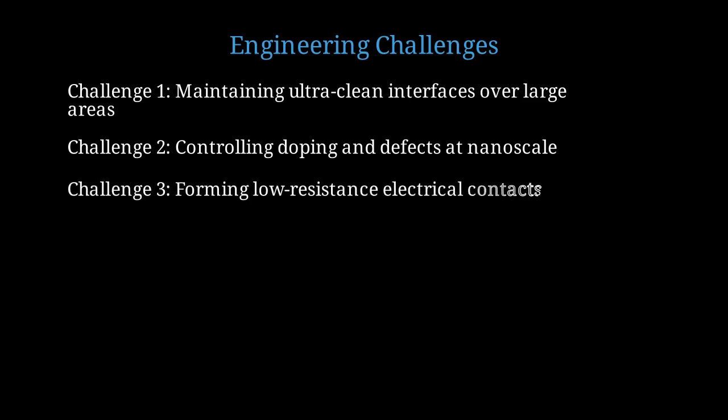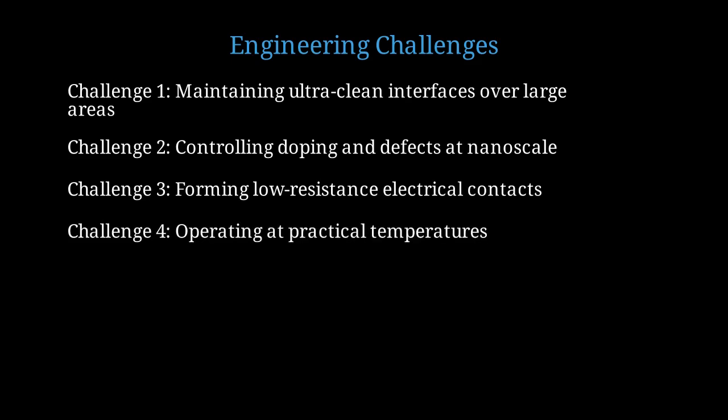Challenge 3 is forming low-resistance electrical contacts. As we've discussed, contact resistance becomes the bottleneck in ballistic devices. Engineering metal semiconductor interfaces with low resistance is extremely challenging. Challenge 4 is operating at practical temperatures. Most applications require room temperature operation, but phonon scattering at 300 Kelvin severely limits the mean free path.